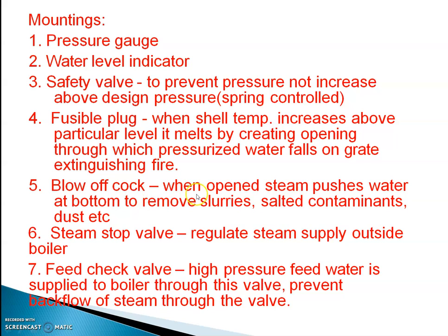When the blow off cock is opened, the steam pushes water at the bottom, removing slurry, salt, contaminants, dust, etc. The steam stop valve also regulates the steam supply outside the boiler. Through the feed check valve, high pressure feed water is supplied to the boiler. This valve prevents backflow of the steam through the valve.